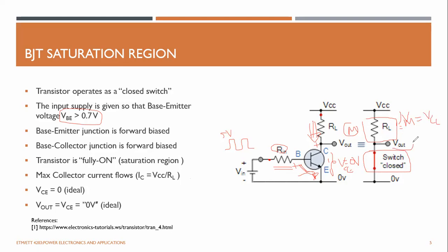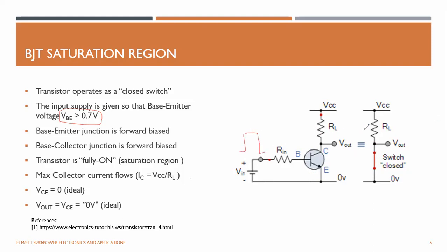Motor voltage is simply VCC. But in logic gates, that is a different case. You take this voltage and it goes to 0, but we are not focusing on that. In a power electronic circuit, remember, if you use a BJT to drive a motor or a relay or any such device, when you provide your control signal to a higher state, a large current will flow that will enable you to drive this VCC across your load.